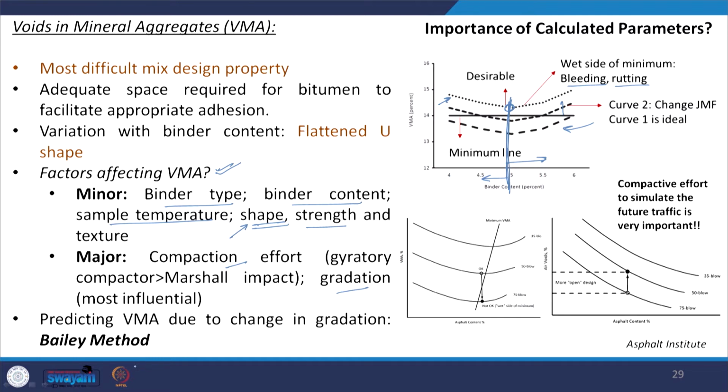What I mean by this, let us say you have some bitumen coated aggregates here. Okay, so this is in a loose state now and you are applying some compaction. Let us say you have applied some form of impact compaction, you have given 10 blows. Once you give 10 blows, aggregate particles will try to move and orient themselves and the density will increase.